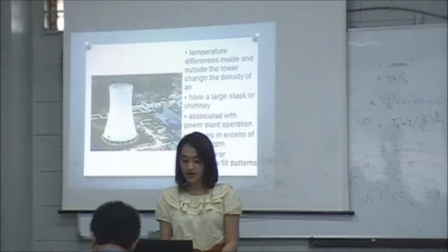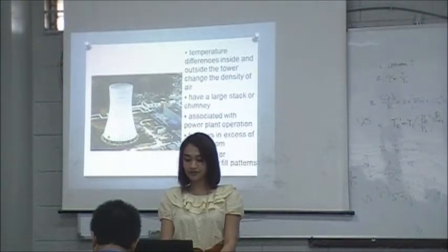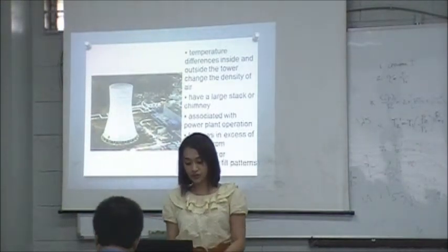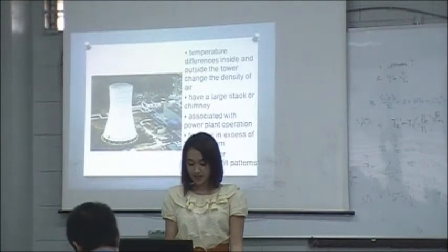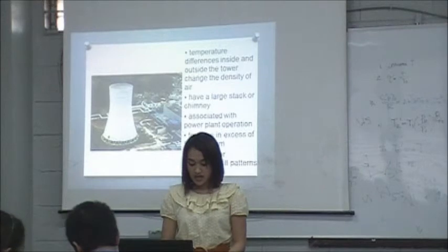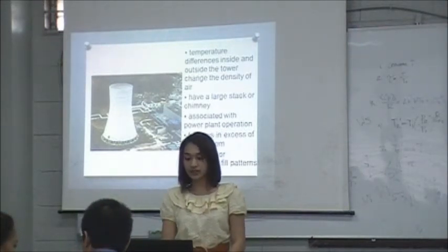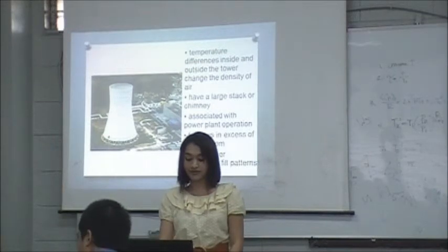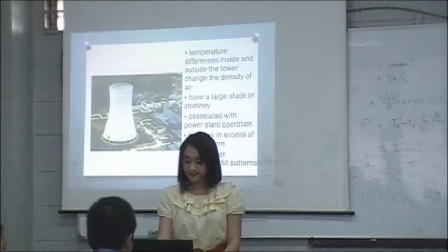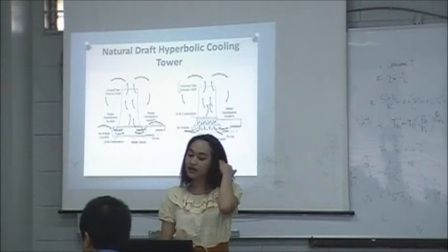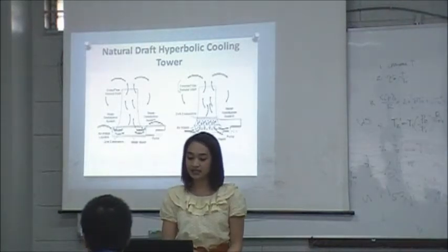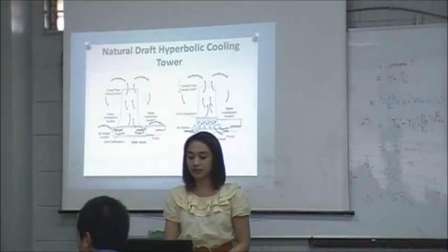In the counterflow design, evaporative heat transfer is more efficient, because water is always in contact with the coolest air and a minimum amount of film is required. This is the mechanism inside the natural draft hyperbolic cooling tower.